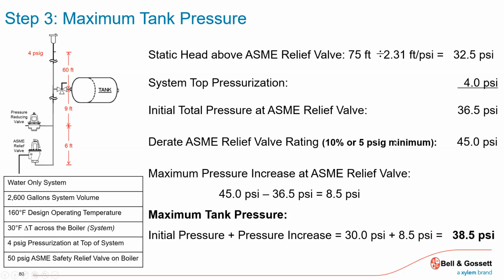So in this case, knock it down 5 pounds, so we say 45, just a safety factor. The relief valve is still 50, but traditionally they know it's sitting there almost ready to go, and it might start weeping. So if we take that 10% out of the sizing, it gives us a little cushion to make sure that valve doesn't open.